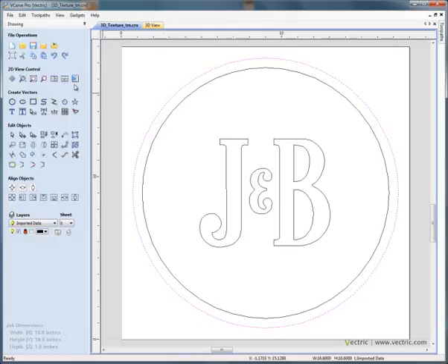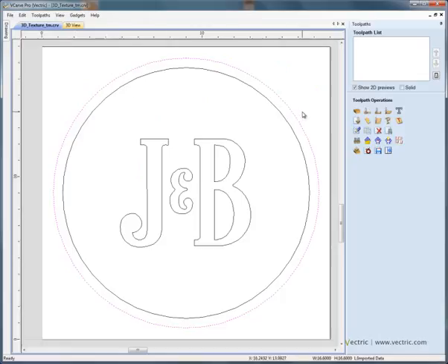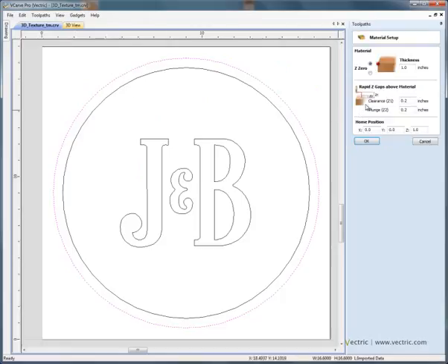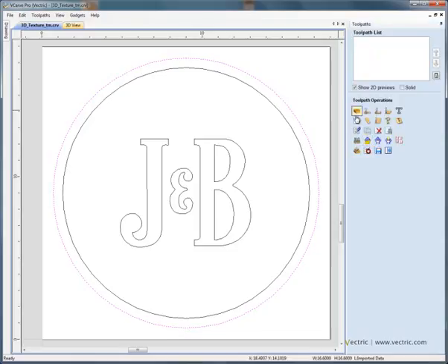Okay, we're going to swap from the drawing tab on the left to the toolpath tab on the right. On the toolpath tab we set up our material settings, so 1 inch thick material, and set up the clearance heights and the retract height for the home position. The first row of icons are for the two-dimensional toolpaths such as profiling, pocketing, drilling and quick engrave. The second row are our 2.5D/3D toolpaths, so 3D V-carving, fluting, 3D texturing, raised prismatic lettering and also our inlay toolpaths.